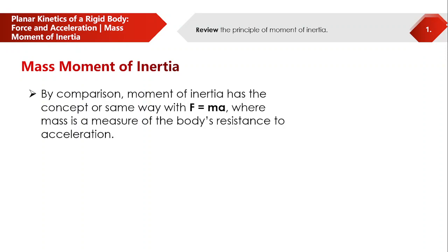No? It resists the angular acceleration of the motion. So it is the same sense as F = ma, which is M = Iα. Your F is the moment, your m is the mass moment of inertia, and your acceleration is the angular acceleration when we are talking about mass moment of inertia.